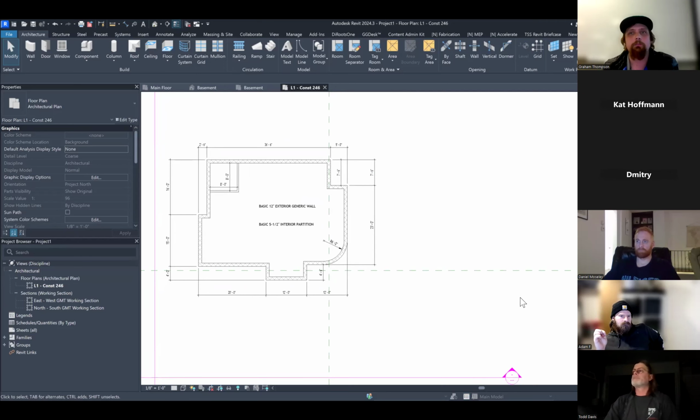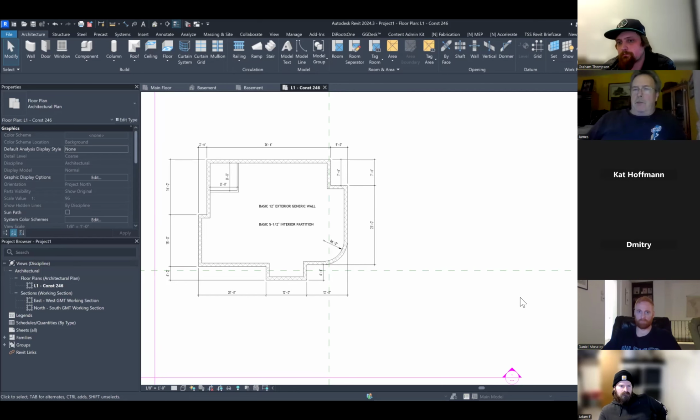So when you're estimating, were you taught any place to start on the drawings? Or was it just kind of start looking at the drawings and start counting things? Start at the top left corner and go clockwise. Okay. So that's the exact same method that I use here, and that all stems from my days of estimating. Every time I look at a set of plans, that's how I view it.